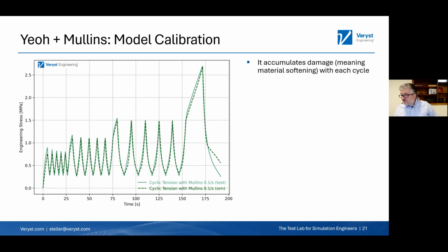How many elements are used to capture the frequency range? You know, I generally use one relaxation time per decade of frequency. That can usually get me what I need, and so that's my rule of thumb. There are always going to be exceptions to that, but that's my rule of thumb.